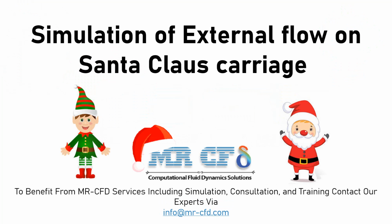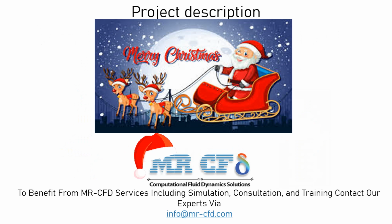In this project, we will simulate the passage of external airflow on Santa Claus carriage. In this project, the external airflow around the Santa's carriage has been investigated. The airflow enters the computational domain with the velocity of 30 meters per second and passes over the carriage. Realizable k-epsilon model with the standard wall functions is exploited to solve the turbulent flow equations.